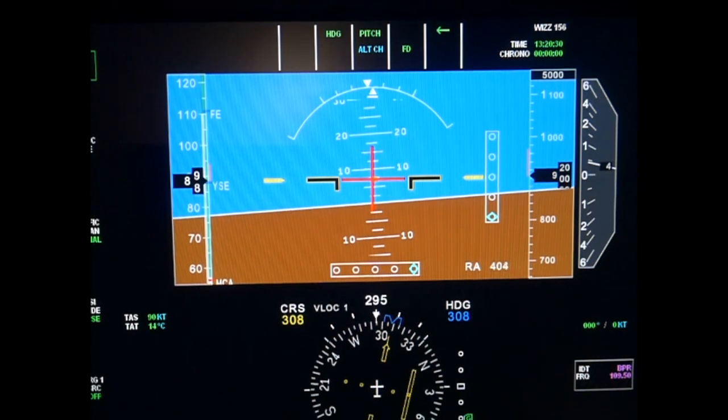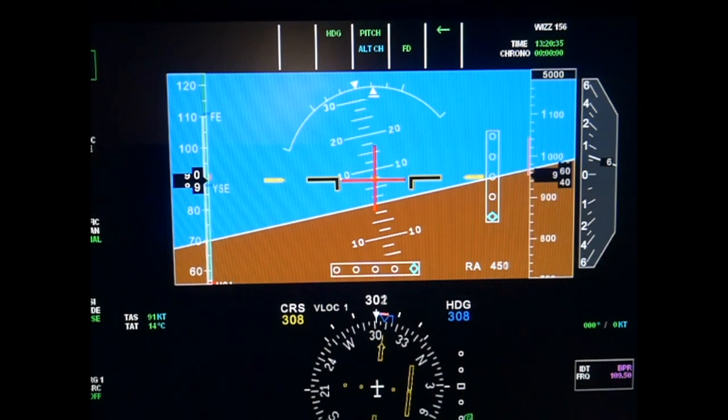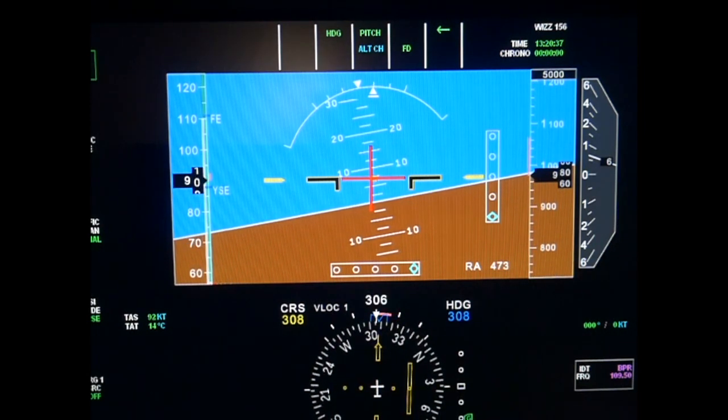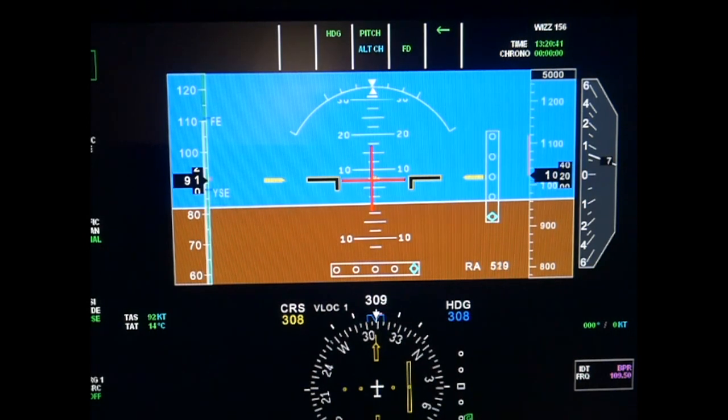In order to maintain the runway heading, heading mode, or if navigation aid is available, nav mode can be selected. Alt change mode will be armed as well. Caution: during go-around, power should be applied manually by the pilot.